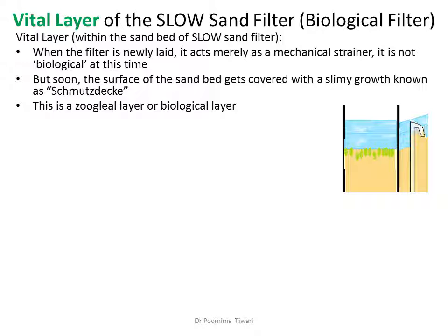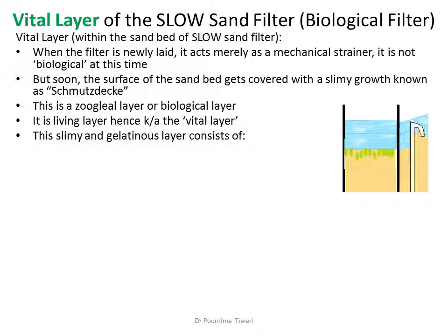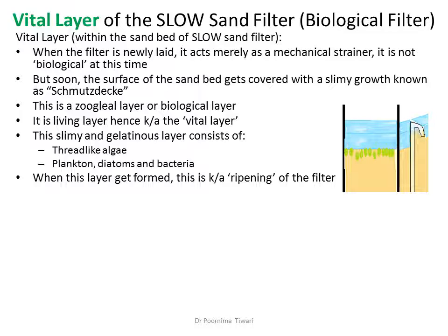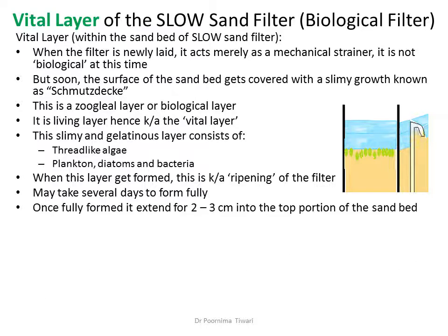This is a zoogleal layer or the biological layer. It is a living layer and hence known as the vital layer. This is slimy and gelatinous and consists of thread-like algae, plankton, diatoms and bacteria. When this layer gets formed, it is known that the ripening of the filter has occurred. The layer may take several days to fully form, and once it is fully formed, it extends 2 to 3 centimeters into the top portion of the sand bed.